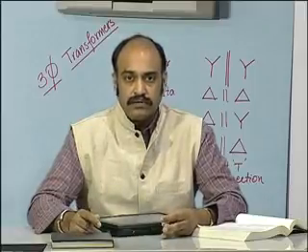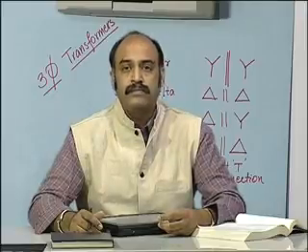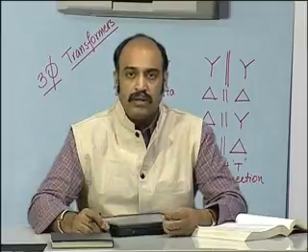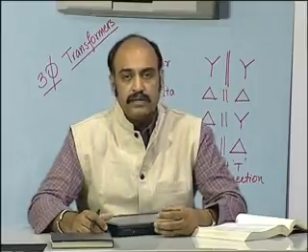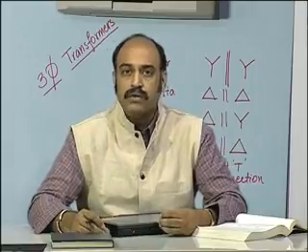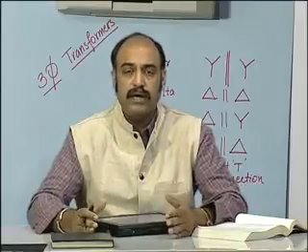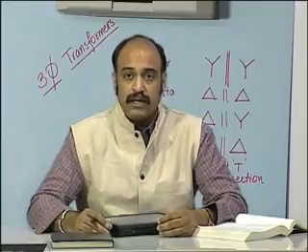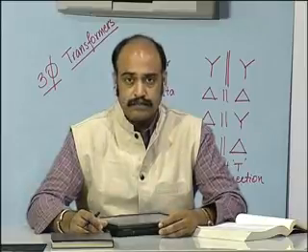The Faraday's law of electromagnetics, that is E is equal to n d phi by dt, the Ampere's law, and all the notions of leakage inductance, the mutual inductance, the core loss, the hysteresis loop, all those concepts that we studied in the single phase transformers are equally applicable to the three phase transformers also. In fact, the equivalent circuit will also be similar.